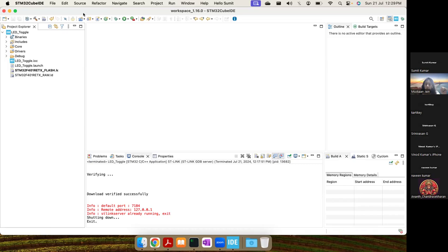Now talking about NMOS. NMOS is on when VG, which is the gate voltage, is more than the source voltage. That is when we are pulling the pin low. So you see, we do not need pull-up, pull-down resistors in this case. For safety purposes, ST have kept a resistor, whose range you can see in the data sheet or in the schematic. The actual value is generally between 200 to 500 ohms. And that's how we are switching our LED on and off. Over to you, Sumit.